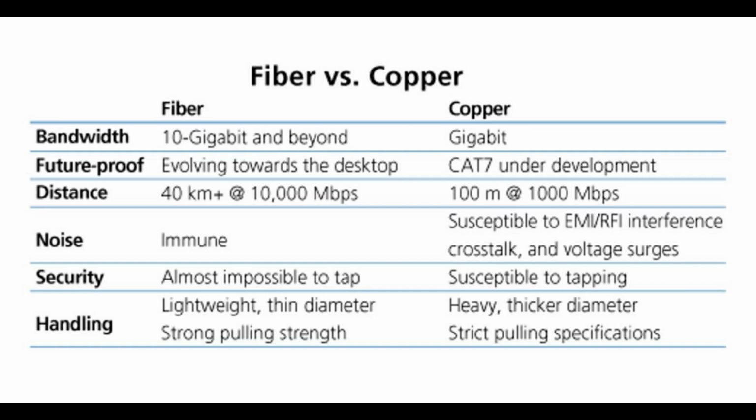Here are the main components and features of an optical fiber cable. 1. Optical fibers. Material: the fibers are typically made of glass or plastic. Glass fibers are more common in high-performance applications due to their lower signal loss. Core and cladding: an optical fiber consists of a core, the inner part, and a cladding, the outer part. The core is where the light signals travel, and the cladding is designed to keep the light within the core by reflecting it. This structure enables the principle of total internal reflection for efficient signal transmission.